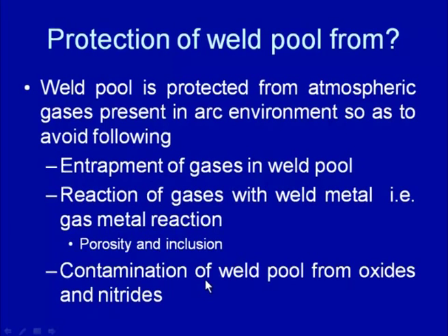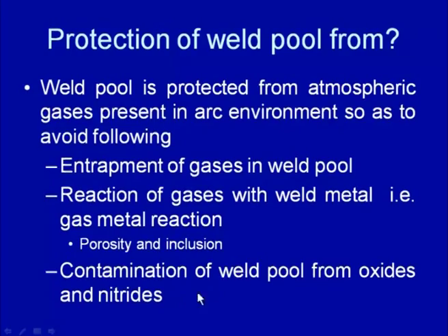If these microconstituents in the solid state are not separated from the weld pool, they will be present in the form of inclusions, which will act as a site of weakness and increase the stress concentration, deteriorating the mechanical performance as well as the corrosion resistance of the weld joints. That is why it becomes mandatory and important to protect the weld pool from atmospheric contamination.